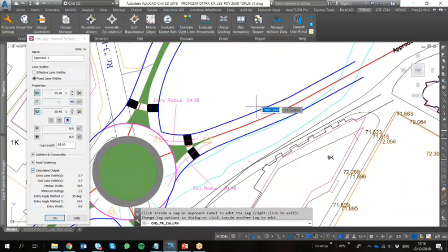So what I have here is that I'm designing now according to the fixed lane width, and this means that if I go into the settings where I can set the lane width, I will be able to modify that. So here in the properties, you see those settings.